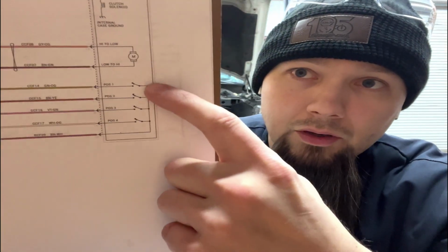Final wrap up on four-wheel drive shift motor actuator thingamabobber, just in case what just happened wasn't clear. I wanted to try to put some better words to it. In a normal scenario, when you roll the four-wheel drive knob, the motor spins and moves the stuff inside. These switches are going to open and close accordingly, depending on the actual position that the motor and transfer case are in. When we actually get it to move into four-wheel drive, we know it is because we saw the front and rear drive shafts rotating together. None of the switches changed at all.